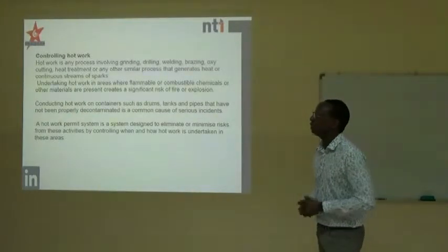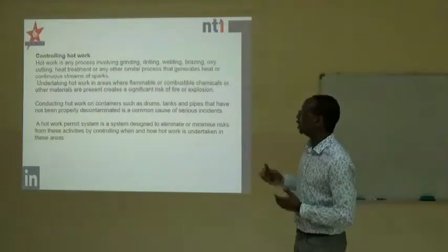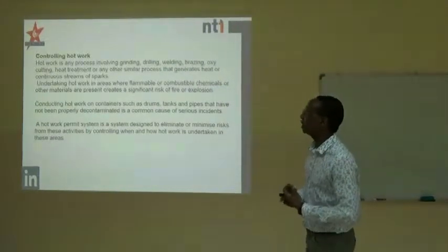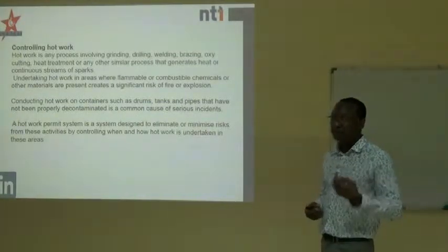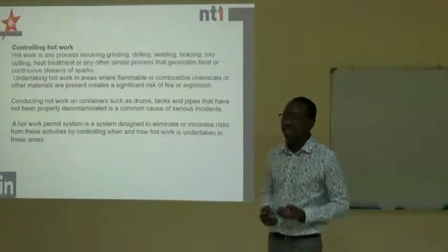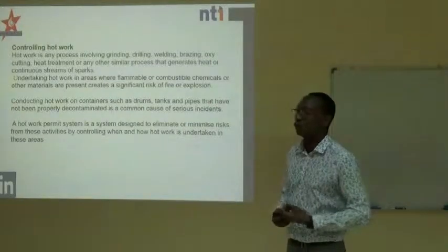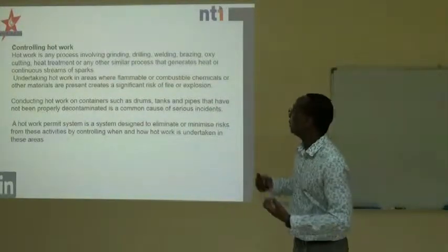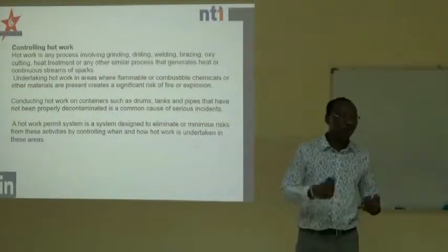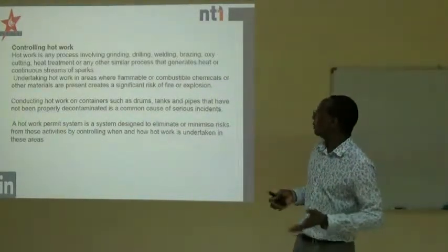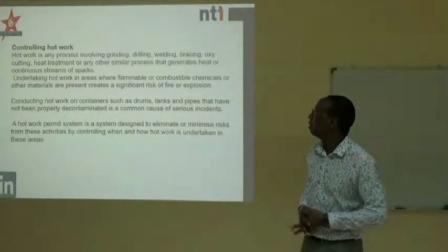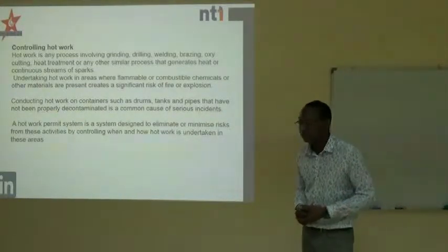Controlling hot work. We've already talked about hot work, but how do we control it? Hot work is any process involving grinding. I think I mentioned earlier that the mechanical guys are mainly involved in hot work. So hot work is any process involving grinding, for instance, drilling, welding, oxycutting, heat treatment, or any other similar process that generates heat or continuous streams of sparks.